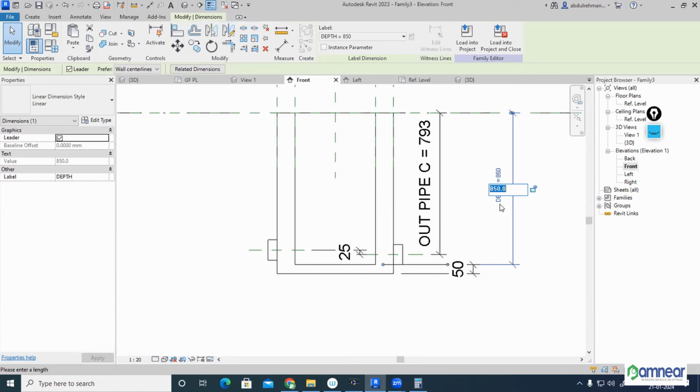or 1:50 slope. But for pipe diameter of 4 inch and above, that is 1/8 inch per foot, or 1%, or 1:100 slope. That's why for each 100 units, you have to tilt your pipe by 1 unit. For each 100 centimeters, 1 centimeter you have to tilt it. So when you are tilting it, the manhole depth will be increasing. If the distance between the manholes is increasing, accordingly the slope value will increase, and the manhole depth will increase. So as per the site condition, when you are doing your modeling, you have to do it like this.